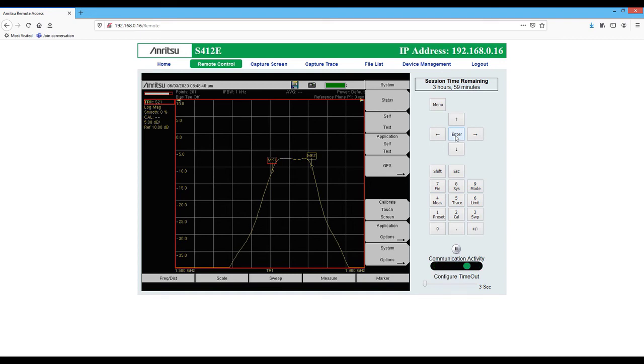But notice, once I did that, everything changed. I went, instead of insertion loss, to what's called S21 log mag, which is basically the levels, the log of the magnitude for S21, which means reading at port 2, originating in port 1. So now all of my things do change quite a bit here.